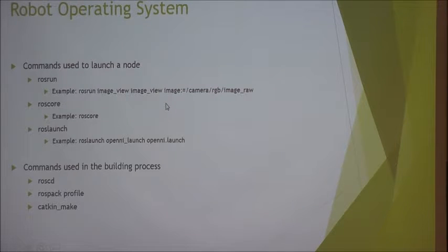Which we'll get more into next time with the working computer. So roslaunch is a combination of these two, and a little bit more. roslaunch starts a ROS master if one does not exist, and it will run a program with a launch file. The launch file actually describes which programs will run.